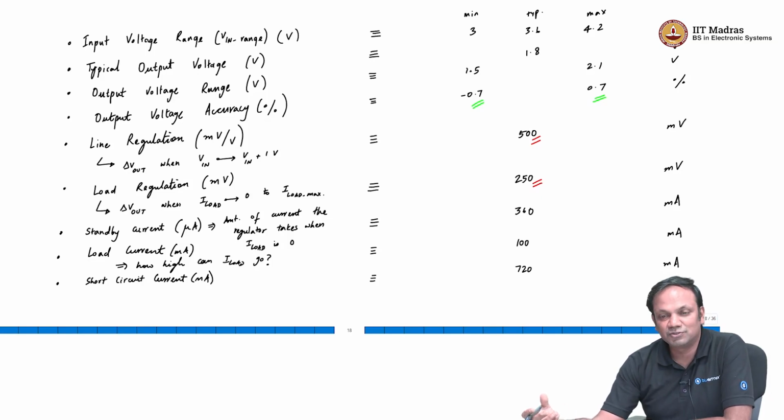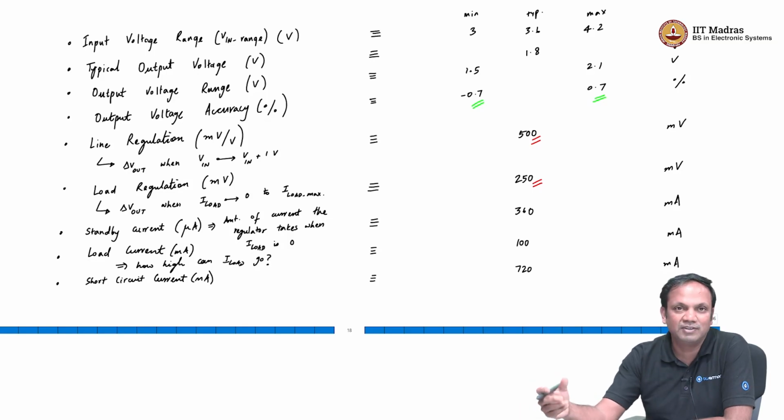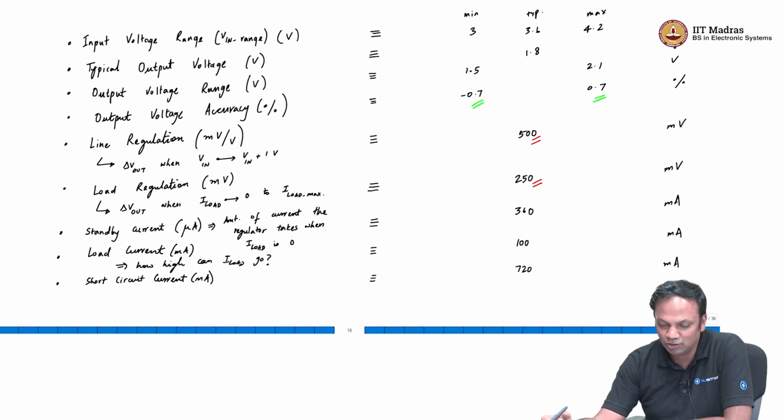And we have chosen very low resistors. We have chosen 5 ohms. Even with 5 ohms, we have a high load regulation. On top of that, we also have an extremely high standby current. If your standby current is 360 milliamps and you have a 1000 mAh battery, then from the time you shut off your device, in 2.5–3 hours your battery will be fully discharged. So, completely unacceptable.